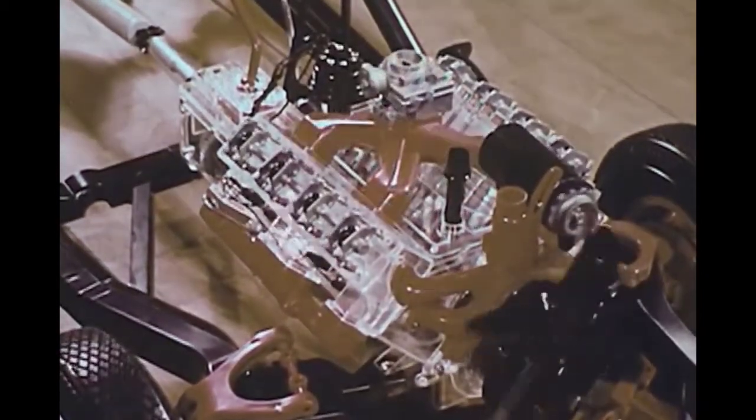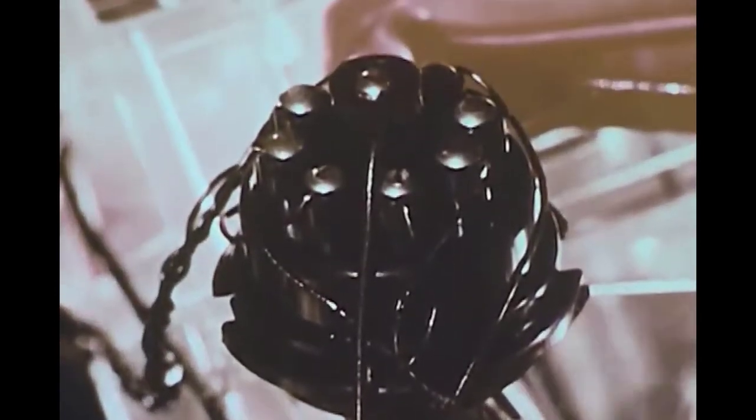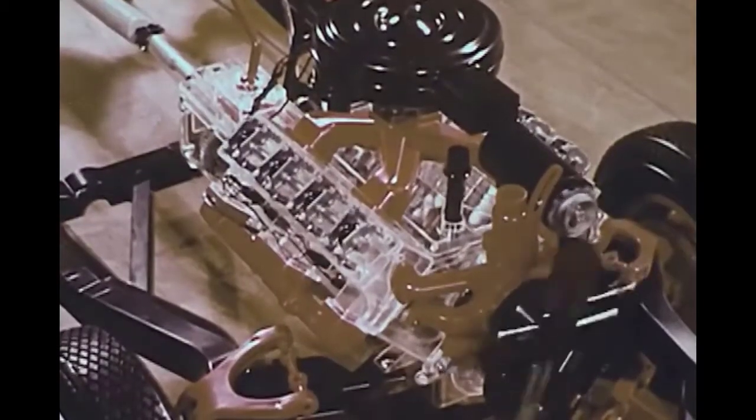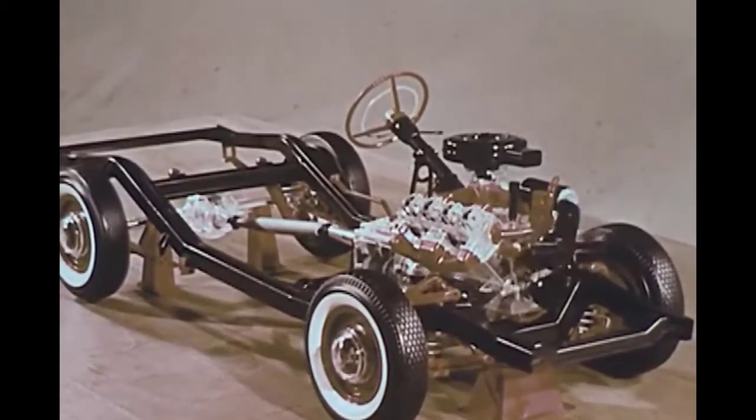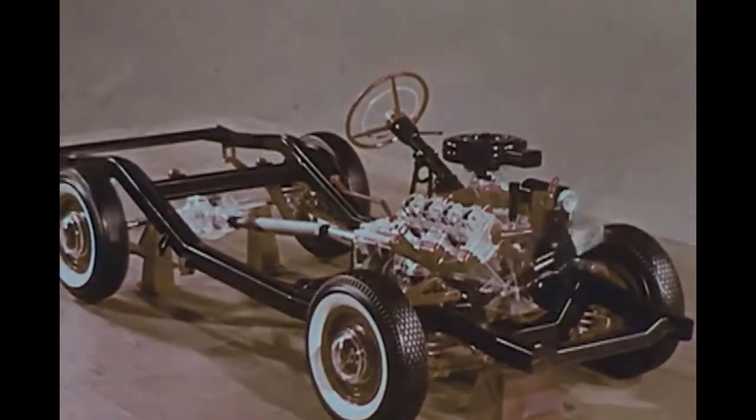Continuing the build-up, here are the carburetor and the manifold. And finally, the air cleaner atop the carburetor. Here is a rear view showing how the pistons drive the crankshaft. And down through the plastic housing, we can see the gearing connecting the camshaft to the distributor. 4, 6, and 8 cylinder engines are standard today. This V8 configuration is very popular for its smoothness.